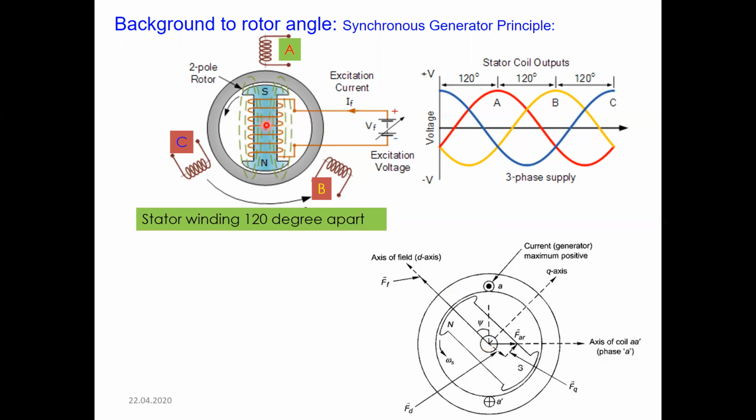So this is the rotor position. And then since it is a salient pole rotor, you have a concentrated field winding along this axis here. So the orientation of the main field, or you can say the concentration of the main field, it is the axis which we call the D axis, direct axis. So this is actually the field axis here, and that is represented by field MMF here. Then the axis 90-degree to this is known as quadrature axis here. So this is Q axis. Now in this axis, when you have the orientation, then you don't have any flux linkage here. It is 0 basically. So the one is the field axis, the main field axis. This is also the D axis, and the 90-degree to this D axis is your quadrature axis here.